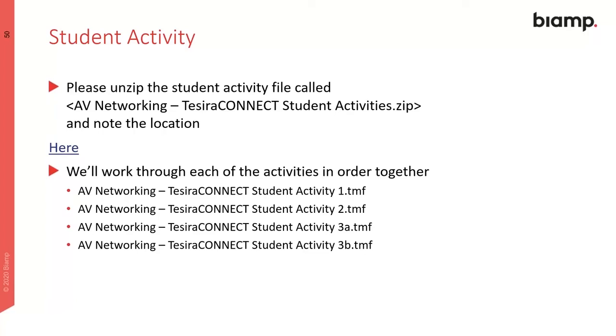So it is automatic. Once you add the TC5D, it pretty much fixes how clocking is done within the system. In the case of other systems, there is an option in the software to assign Dante or AVB as the master. I'll show you in the Dante controller what exactly is happening with the clocking.